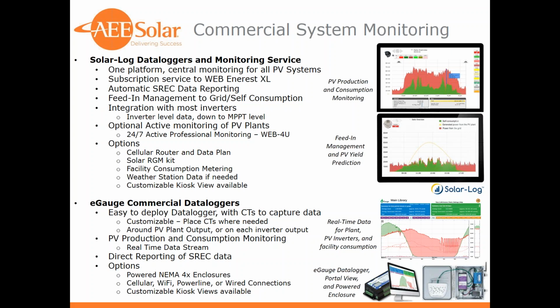One thing to point out is in some feed-in tariff situations, SolarLog can throttle back and regulate the output of the inverter. So in the second display there, you can see that they limited the output of that inverter to match what the consumption is, if that's a concern.